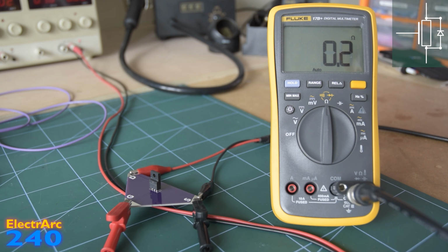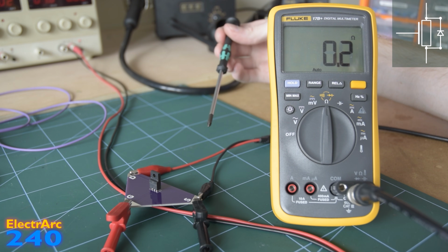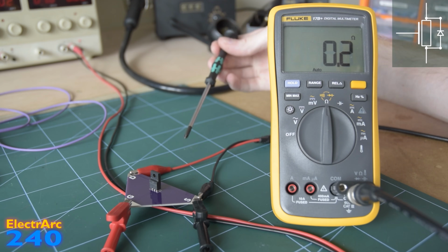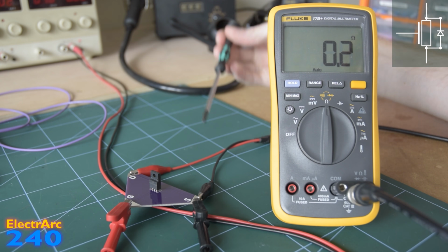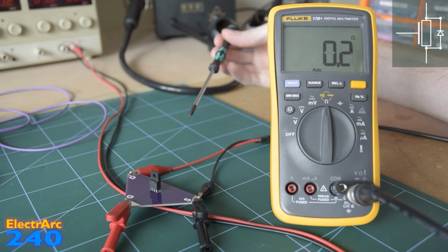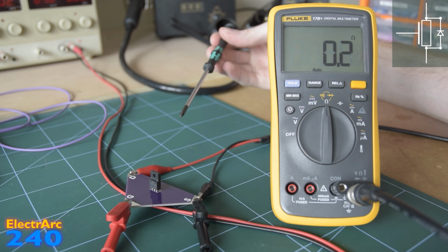So what this shows us is that if we're using a MOSFET as a switch, it's very important that we keep the gate source voltage far away from the threshold voltage, either far above when we want the MOSFET on, or far below when we want the MOSFET off. Sitting around the threshold voltage will hold the MOSFET stuck between off and on, dissipating a lot of power and ultimately leading to its untimely demise.